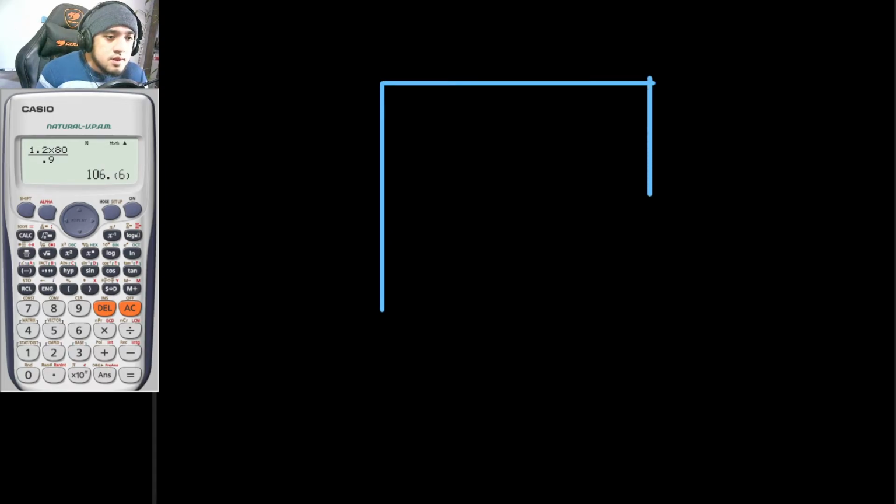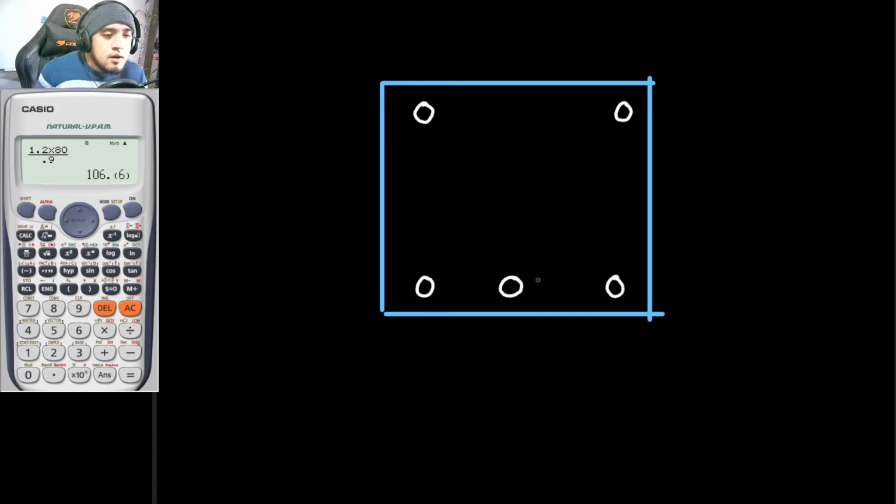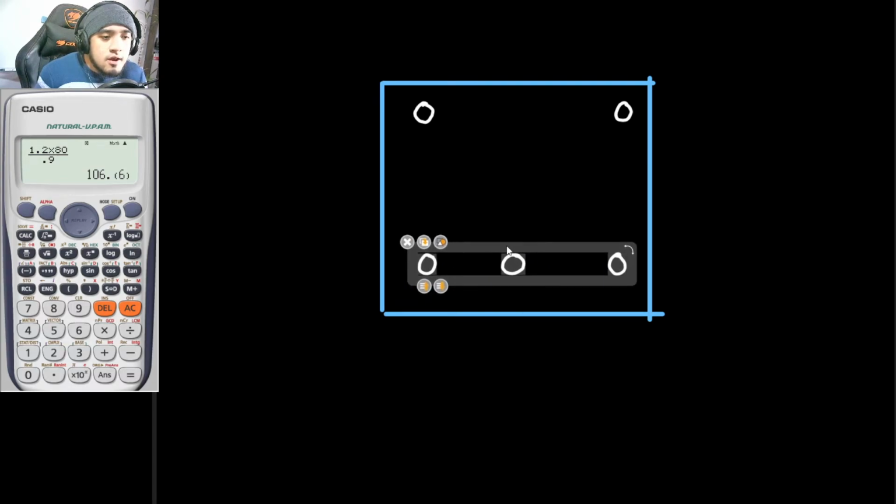For example, that this is to be your section. And we will be placing a rebar here. So a reinforcing steel bar here. A reinforcing steel bar here. Here. Here. And here. But what if during the construction proper, nung ginagawa na siya, yung placement mo nitong bottom bars medyo naitaas mo ng onte. So for example, napunta siya dyan. And if that is to be the case, of course, the nominal moment or the strength of your material will not be the same anymore and will be reduced.